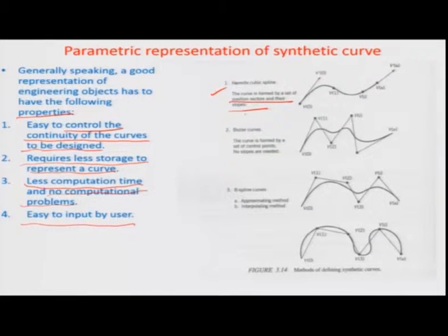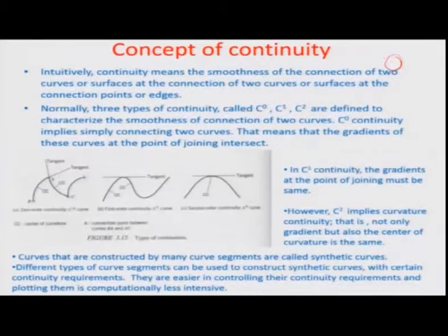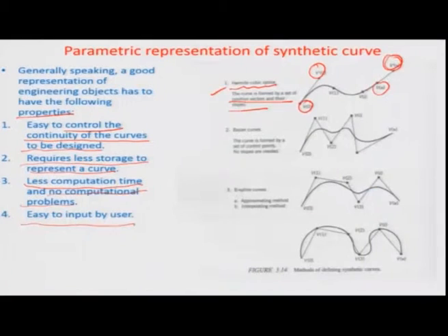When we talk about such a representation of a fit, there are, let us say, two endpoints between which you are trying to fit this particular family of curves. With these endpoints and end slopes into consideration, you can vary either one of them or multiple, so that it generates a bunch of different contours. One of them can eventually suit the part of the profile that you want to fit.